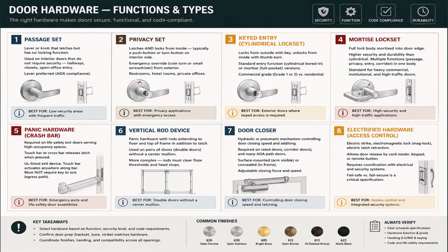Panic hardware, the crash bar, is required on life safety exit doors serving high-occupancy spaces. A touch bar or crossbar releases the latch when pressed. A UL-listed exit device activates anywhere along the bar.